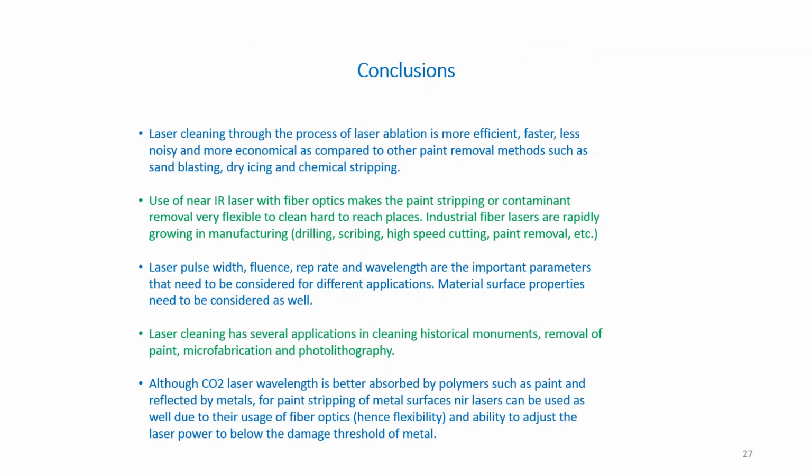And we saw some videos that actually showed that it creates less pollution, it's faster, it's less noisy, it's more efficient. Use of near IR laser with fiber optics makes the paint stripping or contaminant removal very flexible to clean hard to reach places. Industrial fiber lasers are rapidly growing in manufacturing, drilling, scribing, high-speed cutting, paint removal, etc. Laser pulse width, fluence, rep rate, and wavelengths are the important parameters that need to be considered for different applications. Material surface properties need to be considered as well.